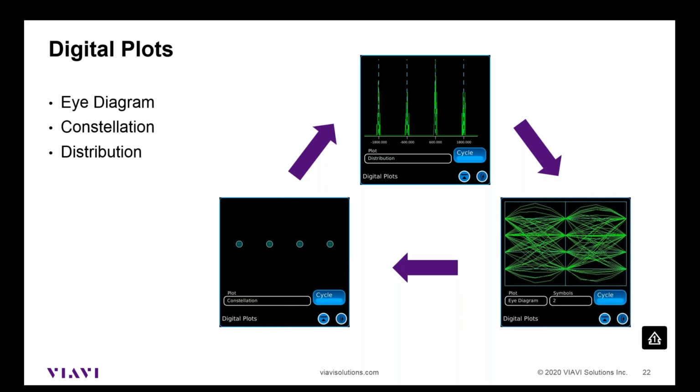The distribution plot, as much as that looks like a spectral display, it's not. It's closer to, I guess, a counter. So we're tallying how frequently each of those symbols is used. And again, this is a P25 signal, so we have 1800 hertz up there for our symbol deviation. So it's something you can use to visualize what that signal is doing. A lot of times you look at a number and it tells you some piece of data, but it doesn't give you the whole picture. A lot of times you can look at these graphical displays and get a better idea what is being measured there and how.